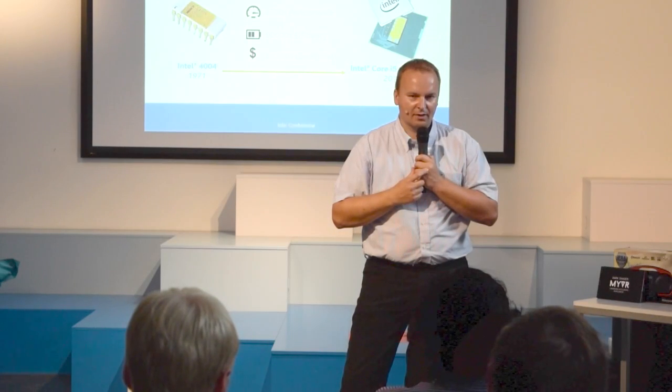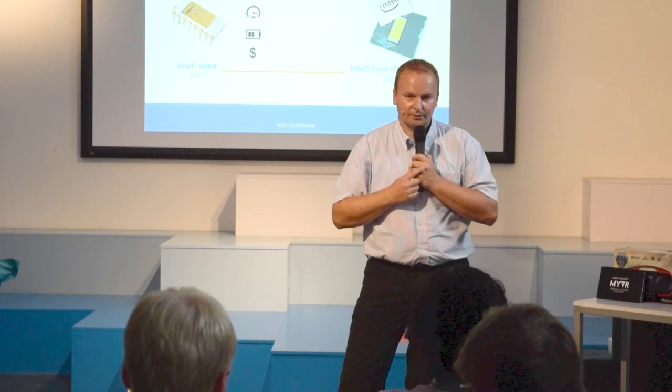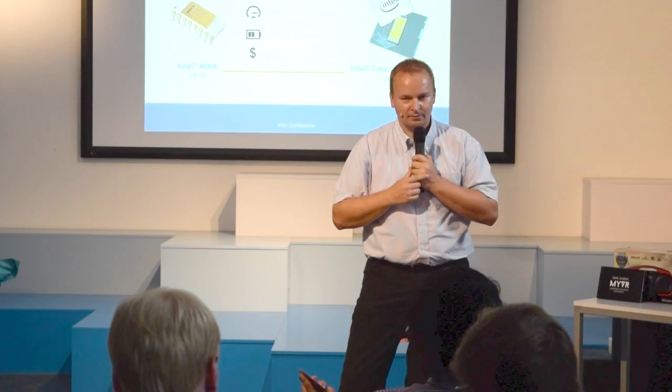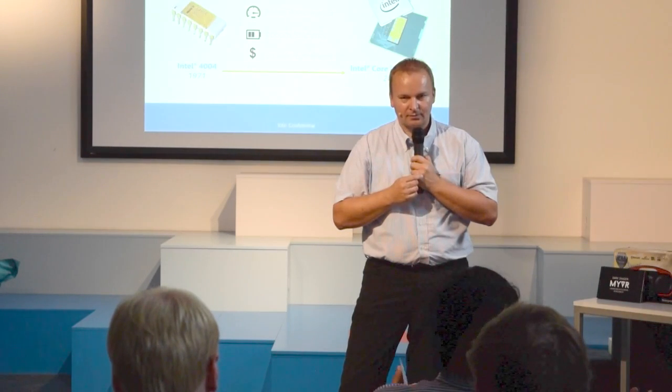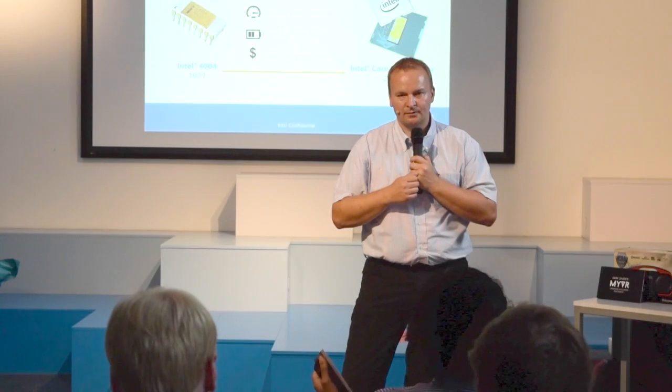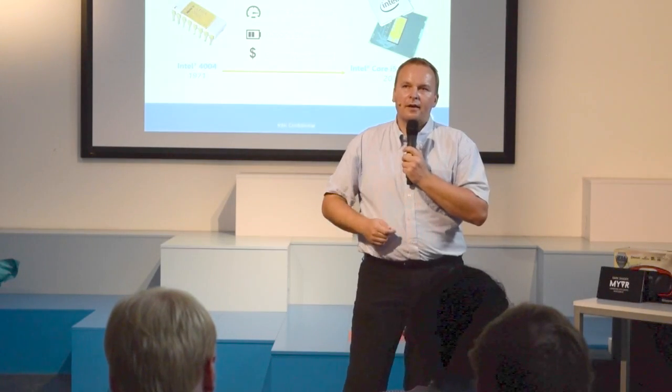And completely unrelated, you showed the photograph of the Arizona facility. So that goes from being built to in production. How long does it take to clean the air inside? Do you know what the process for that is? Actually, it's already built clean, because if you built it dirty, you would never be able to clean it afterwards. So obviously the concrete structures and everything, that's built dirty. But when you start to equip the clean room, you start clean. It's a very complicated and difficult process, also contributing to the cost of the fab.